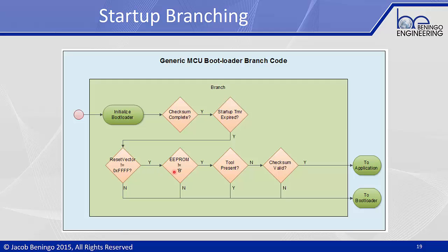Is the EEPROM not equal to B? Is a tool present? And is the checksum valid? And if these things in this flow line check out, then we load the application code. If any of these is false or incorrect, then we load the bootloader, and we await further instructions on how we should proceed.